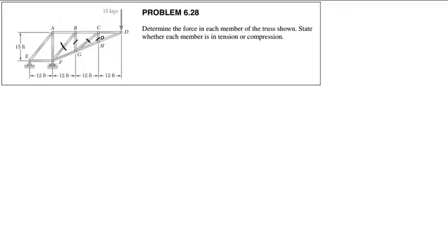Those big, huge concrete columns that go up many stories to carry the flyover ramps on the interchanges. Yeah, some of those do have unbraced lengths that long or much longer, but they're very beefy concrete columns with a very large moment of inertia, which means they're going to be very resistant to buckling, based off of their own moment of inertia and radius of gyration.